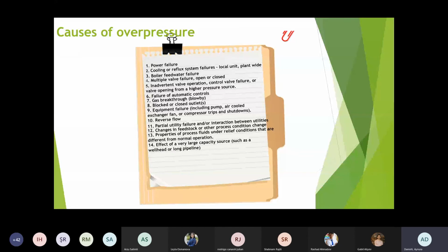If SIS, safety instrumented systems, are used in lieu of mechanical devices, as sometimes happens, a detailed dynamic analysis should be performed to ensure that the downstream system will be protected, given that there is a delay between a high pressure switch activation and closure of the isolation valve.